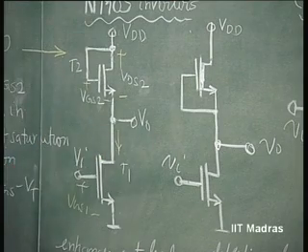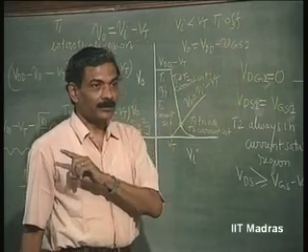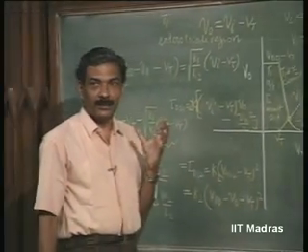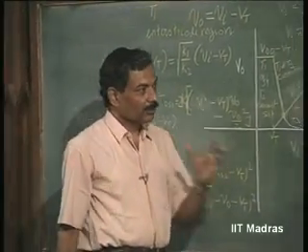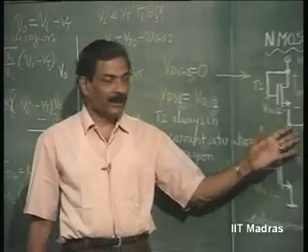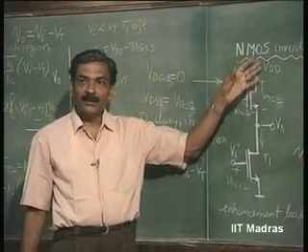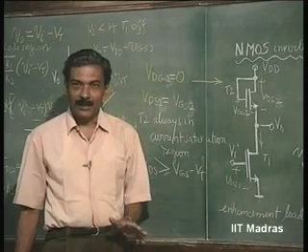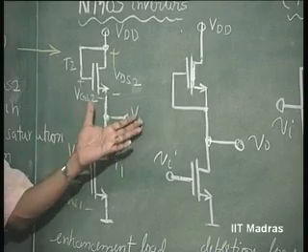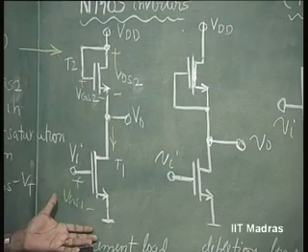This is not small signal gain, this is large signal gain, it is linear. So, because there is a nonlinear characteristic here and there is a nonlinear characteristic here, these two nonlinearities cancel one another and you get a perfectly linear relationship here. Okay.